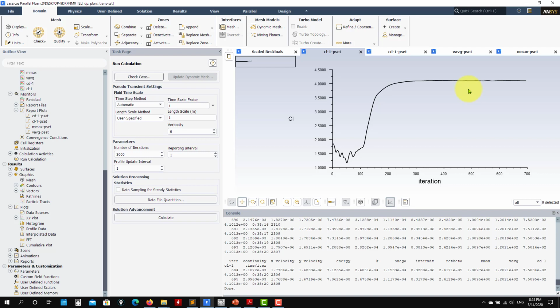One thing you can play around with is the initialization type. When I launched at the beginning, it was standard initialization. This run uses initialization with full multi-grid, so it's much faster. If you use the standard initialization, it will be slower. You will see some larger oscillations, and you will need to wait a long time to get the residuals stabilized, but the result is pretty much the same. So you can play around with the initialization and see its influence on the convergence rate.